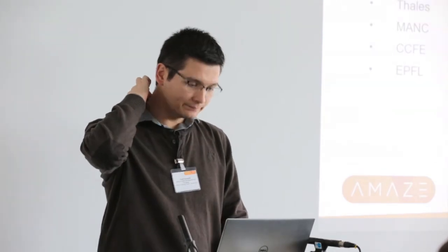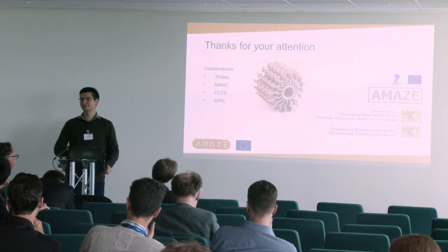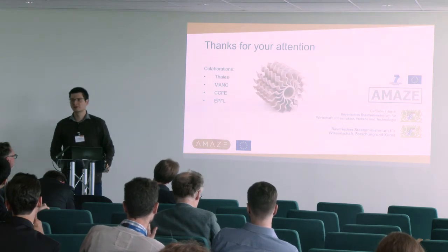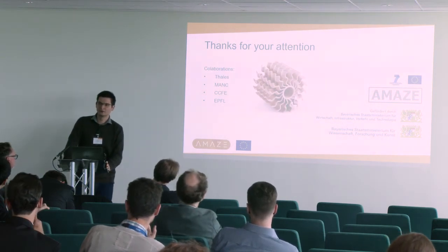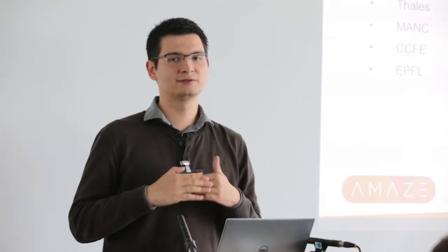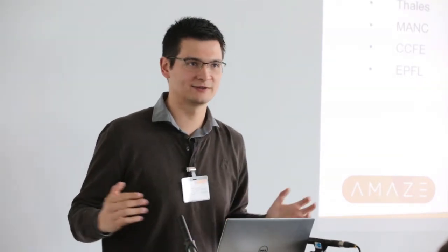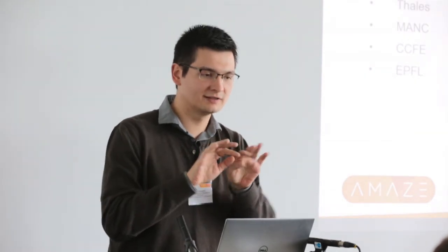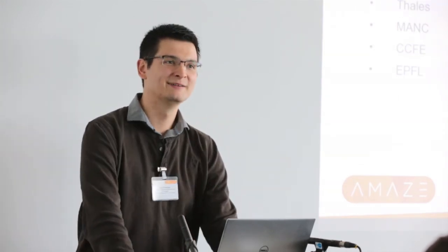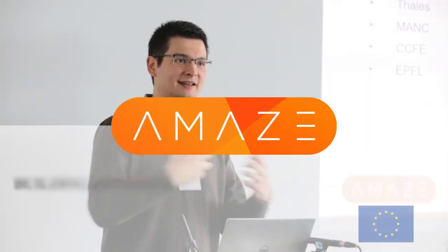Okay. And lastly was the sintered powder. You said you reduced the sintering when you preheat. Yeah, we go to the minimum. So powder removal, is that what you did? Did you smoke? That's the fun part about copper. Every other alloy smokes, basically, if you do it wrong. Copper is very immune to smoke because of its very high thermal conductivity. So you can get smoke, but it's not comparable to what you see with titanium 6-4 or something. It will just move around the beam a little bit, and that's it. So as I said, it's good for our process. This is something that fits the electron beam process very well.